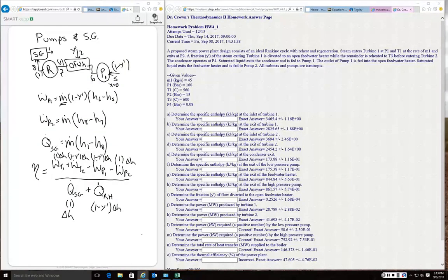And then just finally a concluding remark, when I rewrite the energy equation, first law, what I'm saying with the pumps is that, strictly speaking, if I bring the work to the left side of the equation, there's no change in energy of the control volume, or it's steady state.